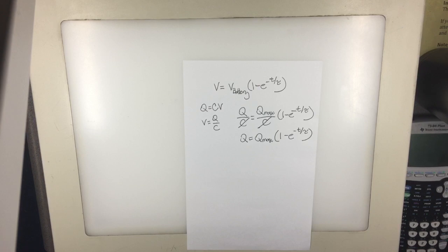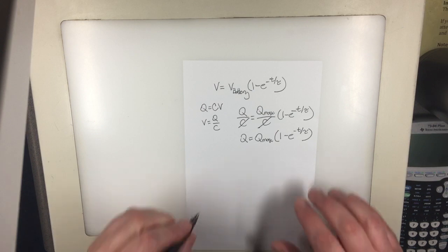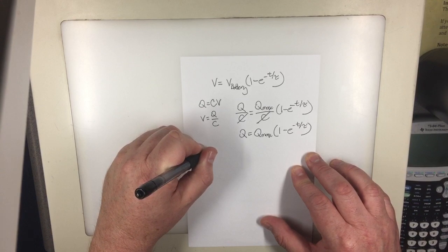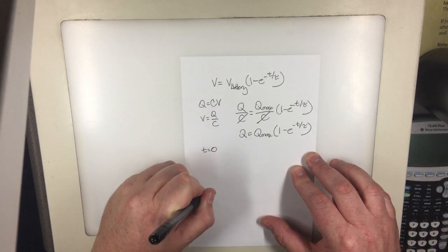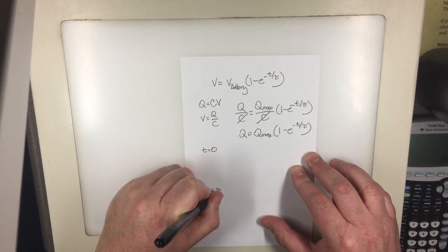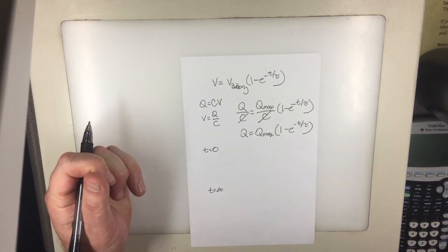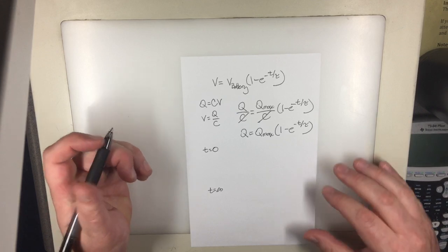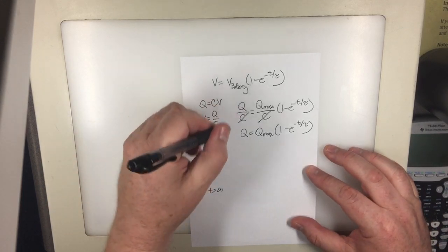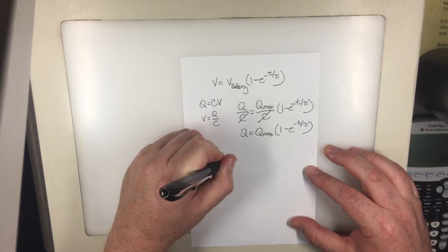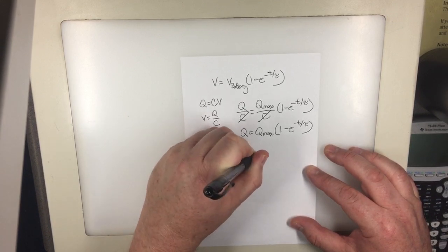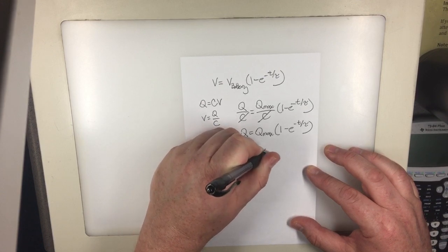This is definitely the charging equation because, as an example, you don't have to do this on the test. I'm just identifying what's going on. You plug in the endpoints. Time will either be 0 or infinity as a test for the equation. If it is 0, this means that V is equal to V of the battery, 1 minus e to the negative 0 over tau.